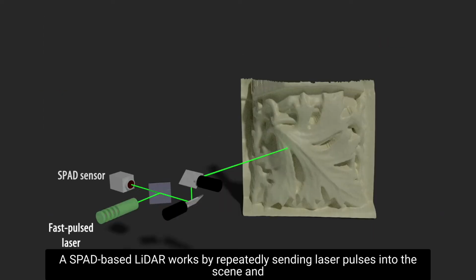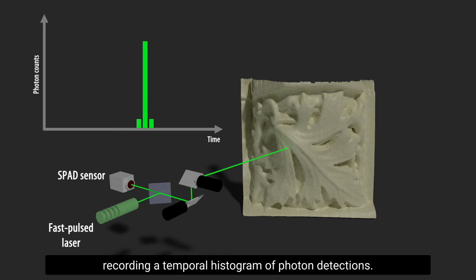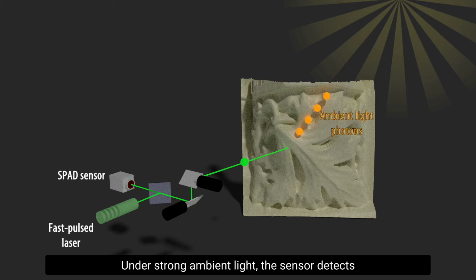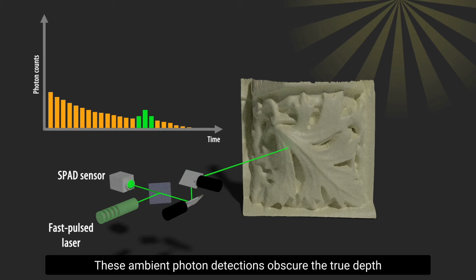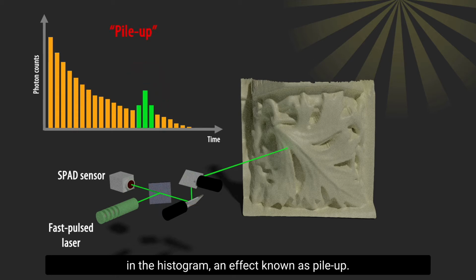A SPAD-based LiDAR works by repeatedly sending laser pulses into the scene and recording a temporal histogram of photon detections. Under strong ambient light, the sensor detects ambient photons more often than laser photons. These ambient photon detections obscure the true depth in the histogram, an effect known as pileup.